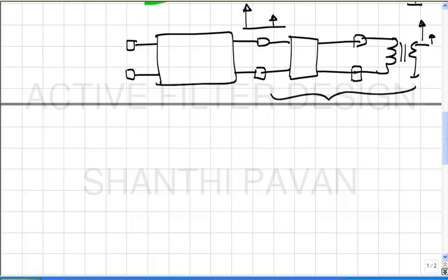For example, if the setup had very low pass behavior, right? I mean, we saw that the frequency response of the external path, that is the cables, all that stuff, didn't really matter, because we were able to account for all of that by having a dummy path and then measuring this path and that path and then divide one by the other, and we are able to get the filter response even when the response of all that path is terribly low pass, right?